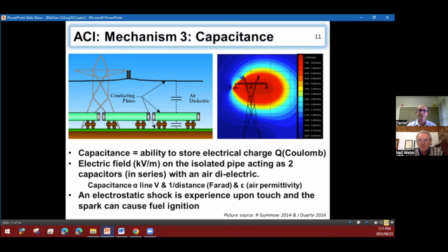The faulted condition is usually phase to ground, and this we regard as a short, a short duration event which lasts as long as the circuit breaker takes, which is automatic. If there's a short, the substation can see the short and the breaker would automatically disconnect. Typically 0.5 of a second down to 0.1 of a second, but often we use 2.5 seconds.